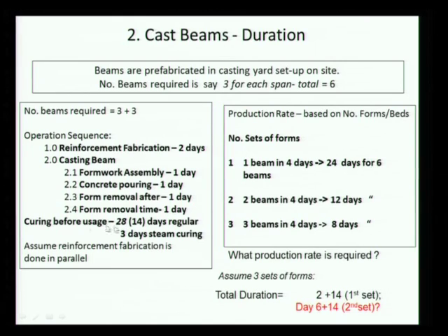Now, curing before usage. The beam is flexural, it's going to be challenged by whatever loads are coming on it, but typically by the time you lift it in place, at 14 days it will attain its full strength, soon enough before the service loads come on it. So generally 14 days is enough. Again, if you really want to take it earlier, you have to use steam curing.